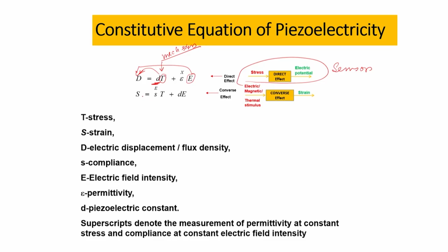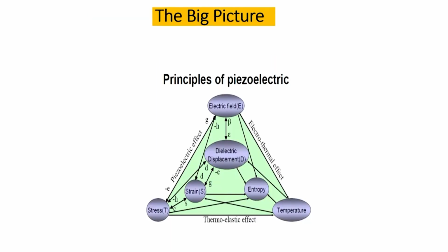Similarly, from the strain point of view, we know that stress generates strain, nothing new in it, but that the electric field generates strain because of this electromechanical coupling coefficient is something important for smart materials. It is also important to know that for every such smart material, it is not just one-to-one, but there is a complex correlation between the electric field, stress and temperature.